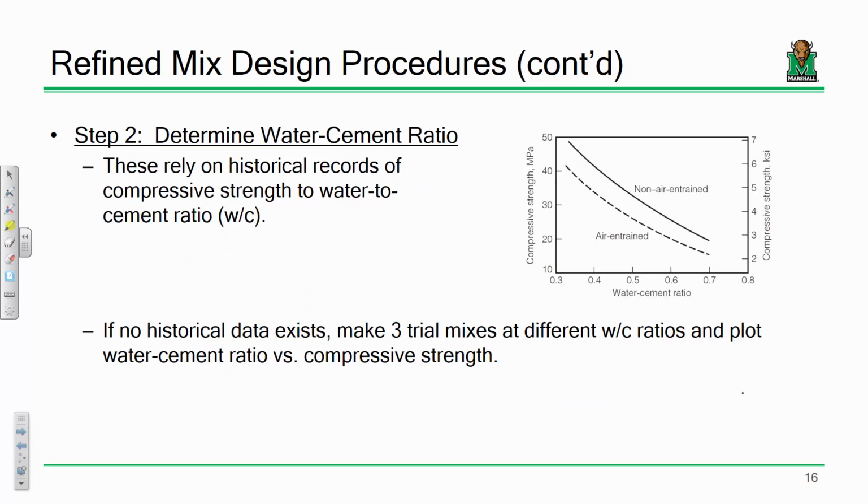All right. Okay. So step one was to determine what we've got to design for. And again, that is always going to be higher than what is specified. The engineer might come in and say, I need a 5,000 PSI batch of concrete. Our design might be 6,200, because we have to account for that scatter, and we have to account for that acceptable risk. Make sense?